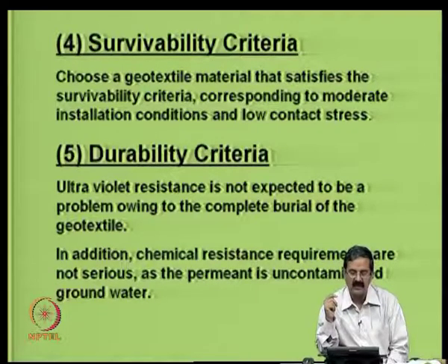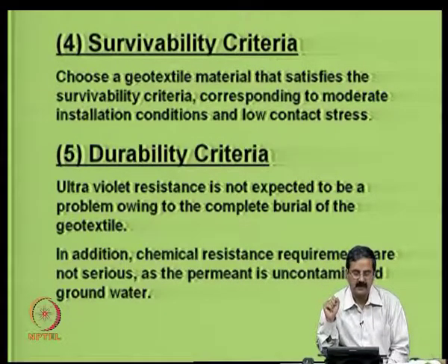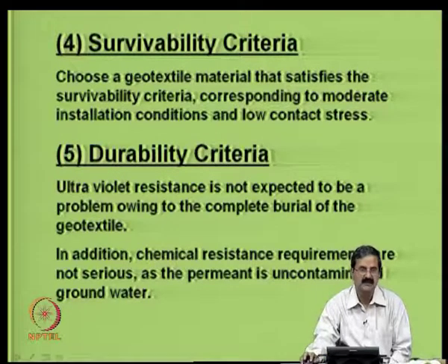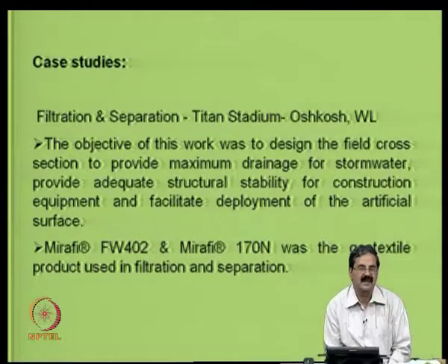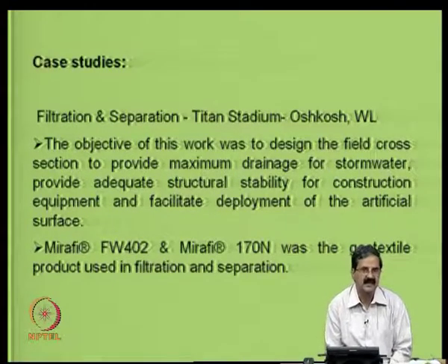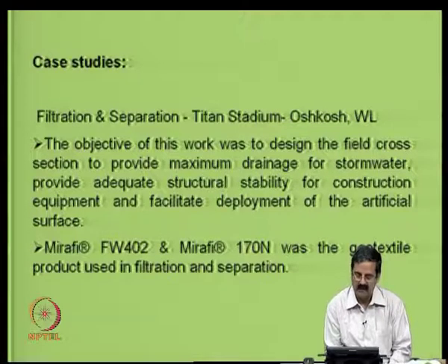If you consider particularly this retaining wall problem, ultraviolet resistance is not expected to be a problem, because you are putting the geotextile in the soil itself; it is not exposed. So, there is no problem of ultraviolet resistance, and even chemical resistance is not serious, because the permeant is uncontaminated, like water is not contaminating this material. So, with these two things, one can understand that yes, one can scientifically design the geotextile reasonably well.